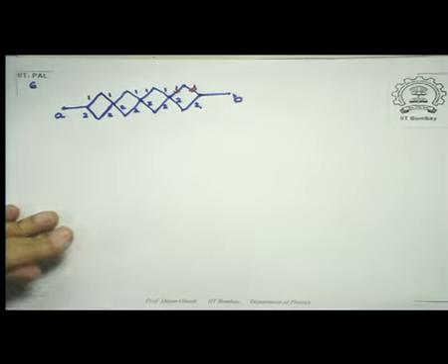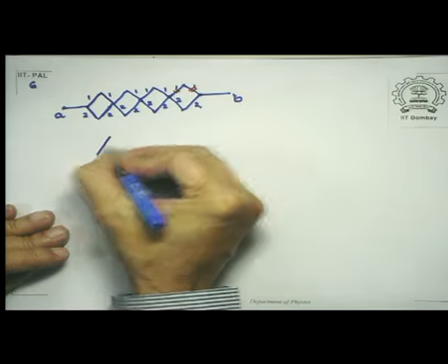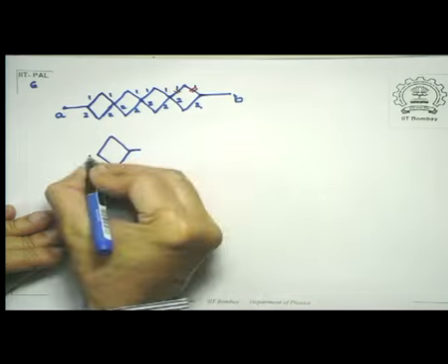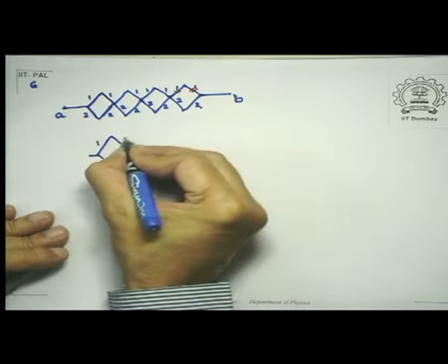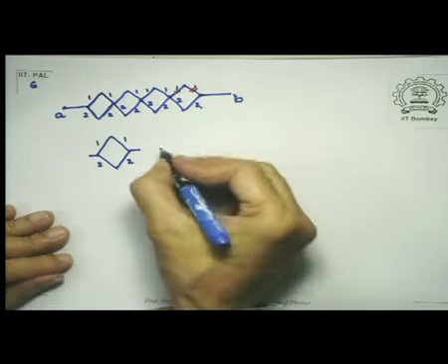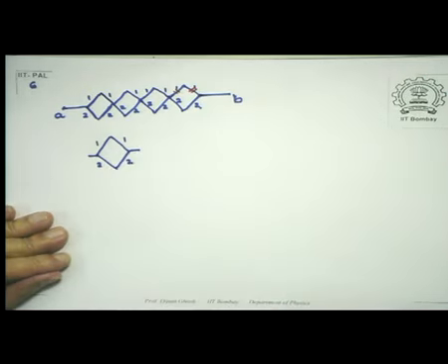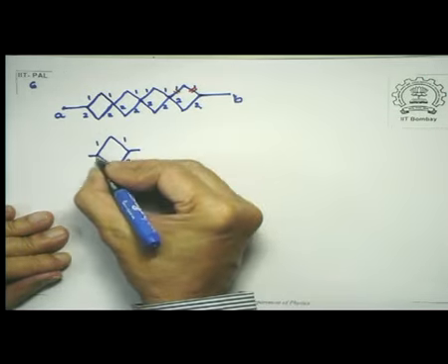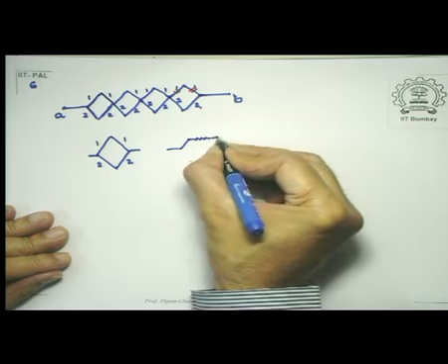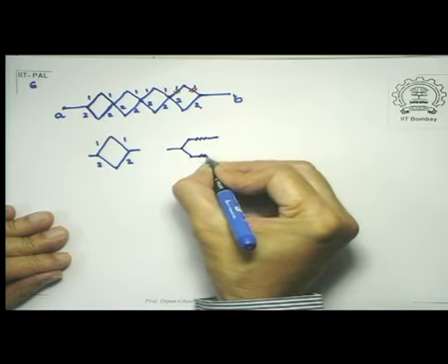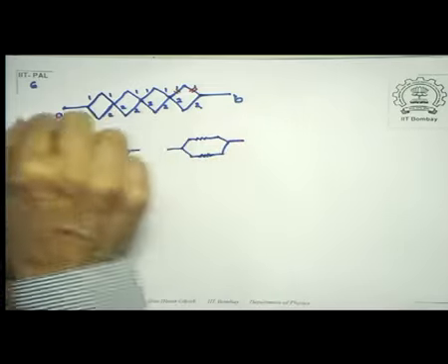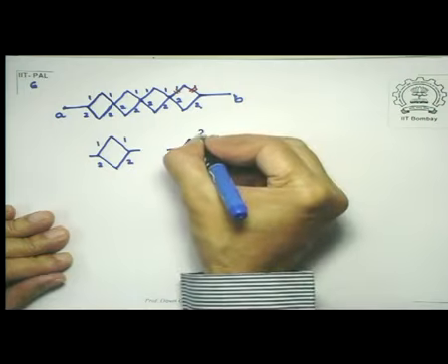So therefore, this section that I have got here, these are connected to the next one. So this is 1, this is 1, this is 2, this is 2. So this is the same as a 2 ohm resistance being parallel to a 4 ohm resistance. So I can redraw this circuit like this. And then of course each of these sections will be connected to the next section and 4 of them will be there. So this is 2 ohms and this is 4 ohms.